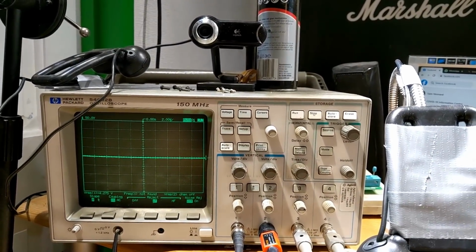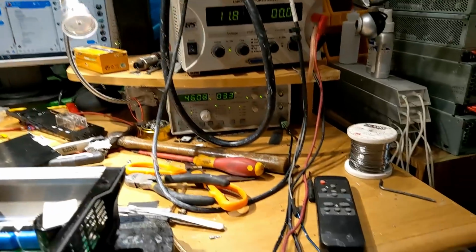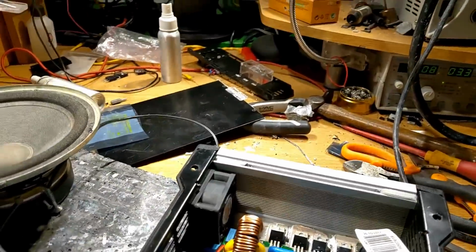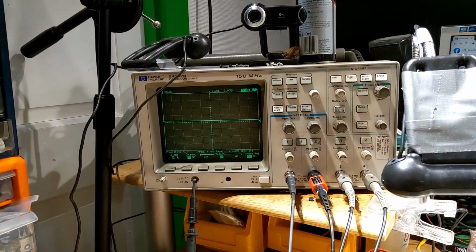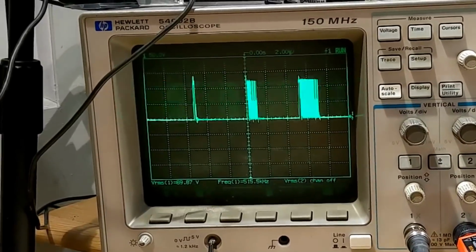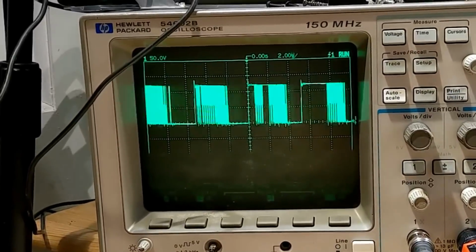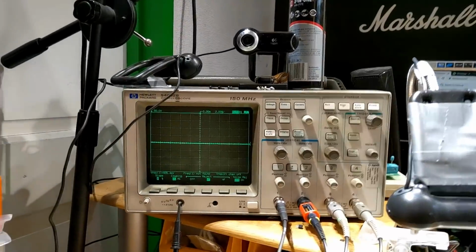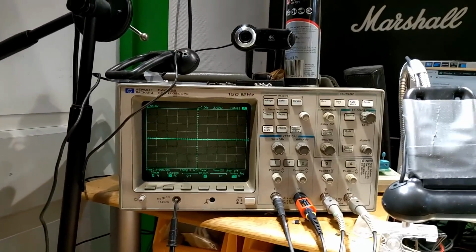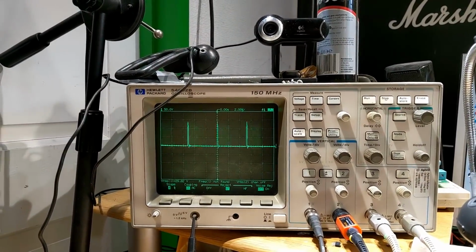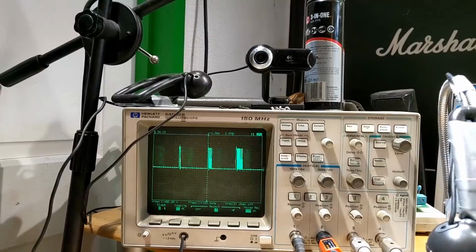So I'm going to apply an audio signal and check what we have on the speaker terminals. Let's grab my RCA here. So now with an audio signal, I was hoping that this would come back to life a bit more like what I'm used to seeing, with a nice square wave on low side drive, low side gate, low side drain, sorry. And no, we actually have the audio modulated there, but it doesn't look like it self oscillates. It's got the audio PWM, the changing in dead time and the changing in duty cycle there. You can see that's what it's meant to do. We've got 46 Hertz going in.